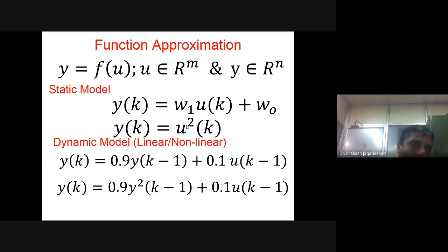And once you have the data, that is the raw data that is available. But before feeding that raw data into, for example, neural networks or deep neural networks, first you have to do data processing. Processing is very, very important, where in data pre-processing, our focus is to suppress the noise, because when you acquire the data from the sensor, the output will be corrupted by noise. So you have to design a suitable filter, and then you have to cull out the measurement noise.